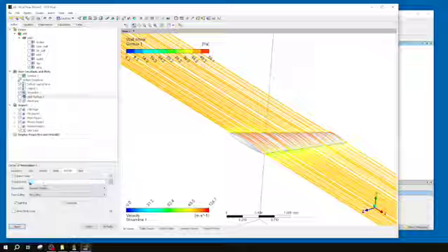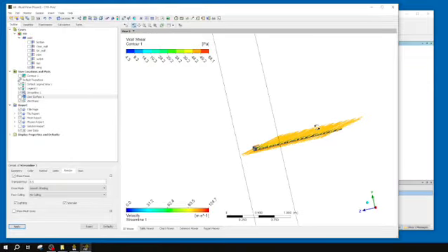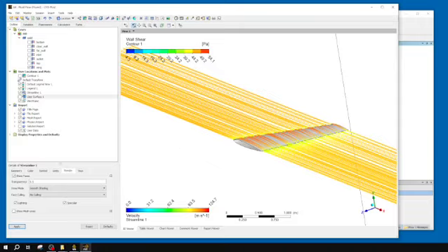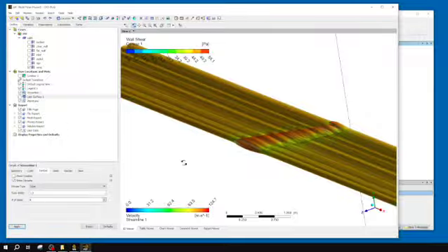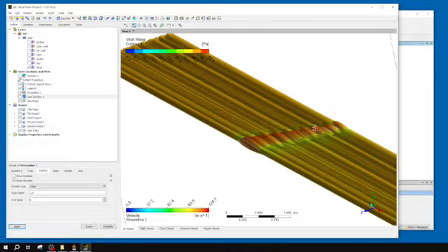If you're displaying something on this surface, or you have a ton of streamlines and want to be able to kind of see into or through them, lines are not the way to go. You should use either a tube or a ribbon. I'll start with tubes. So you can see from that angle, they're very dark.